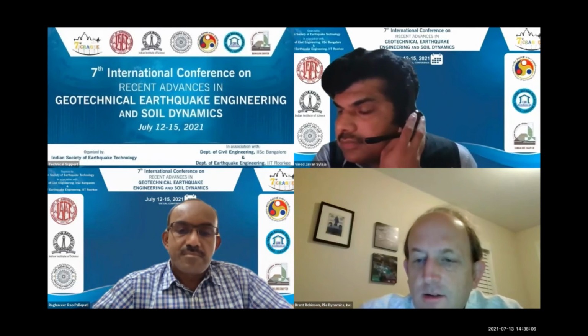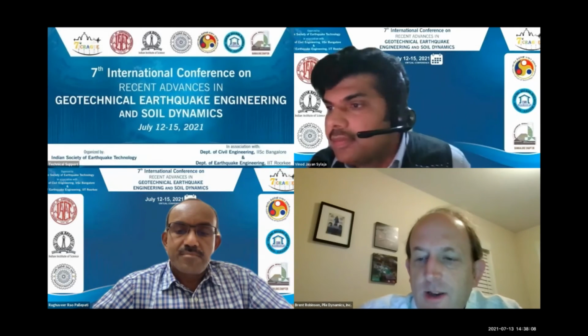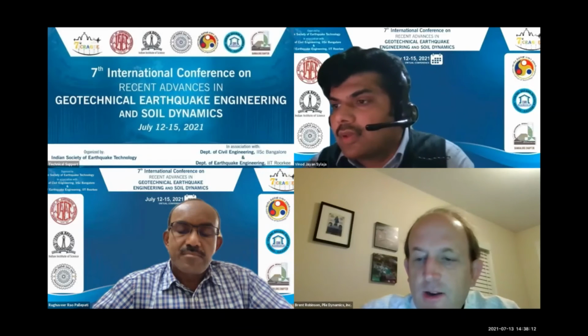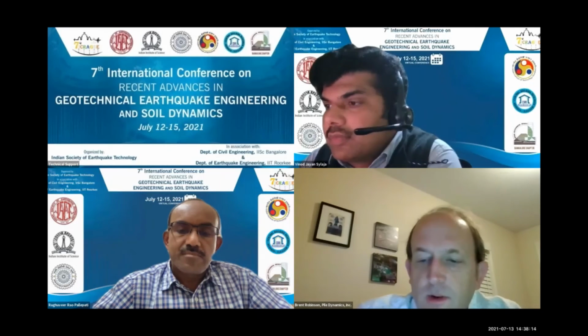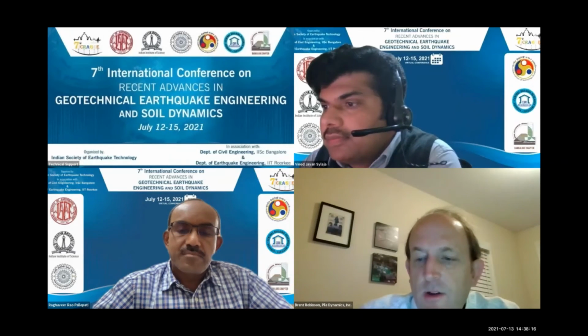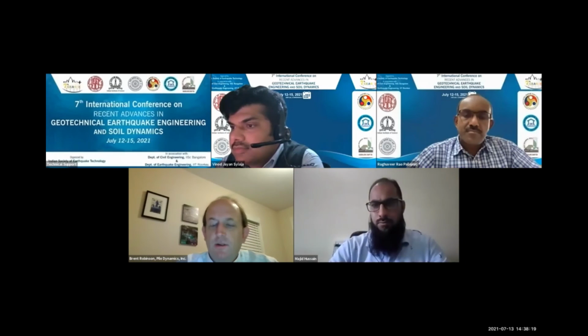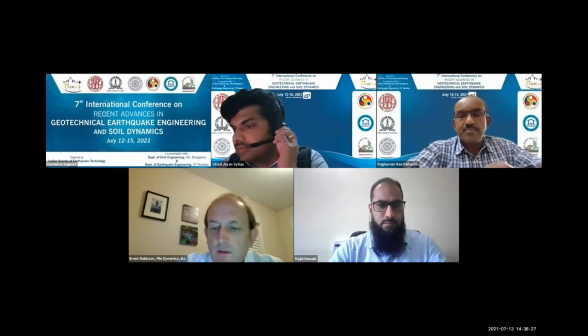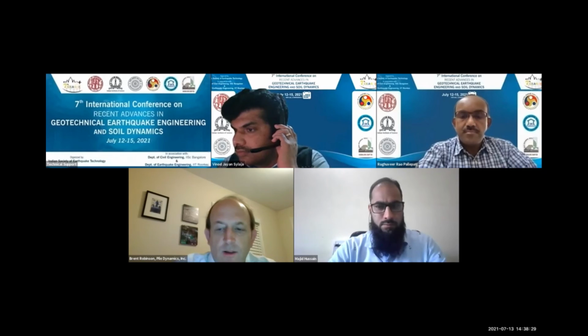Harsha is asking, in general, the tensile strength is the predominant property of geotextiles. And also, we are concerned with the horizontal and vertical elastic modulus of the geotextile and how they are different in their direction of loading. So how do you manage that behavior with a plate element and a linear elastic model?